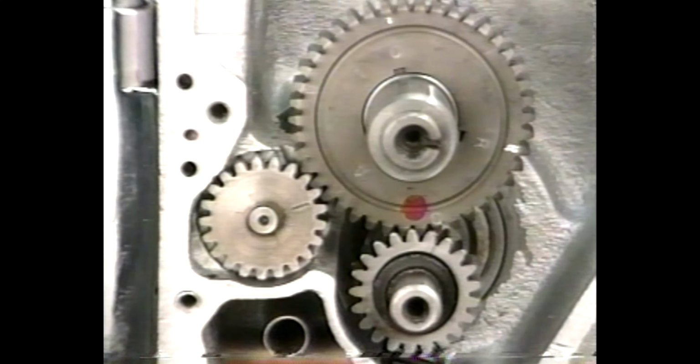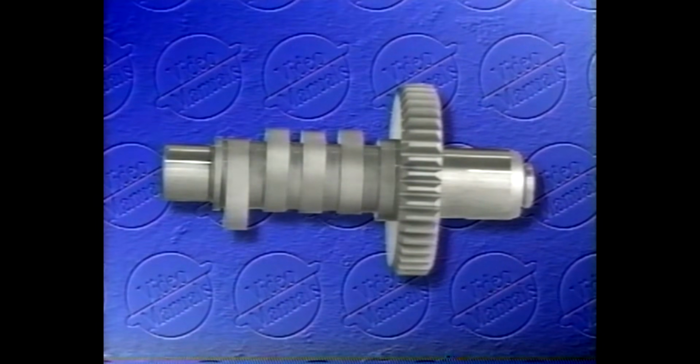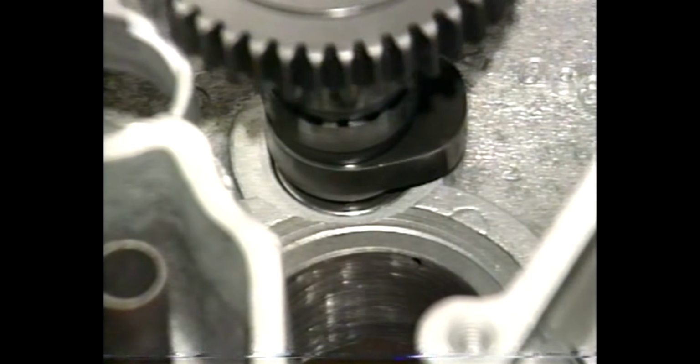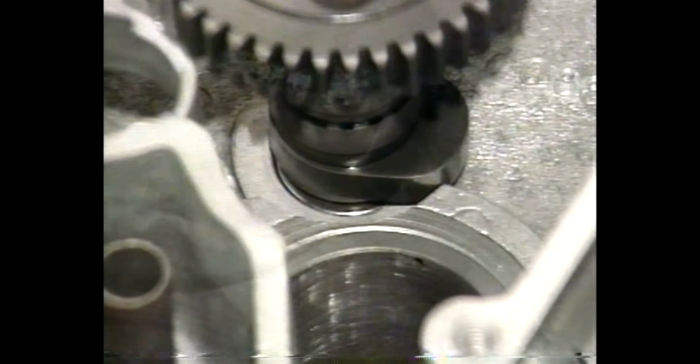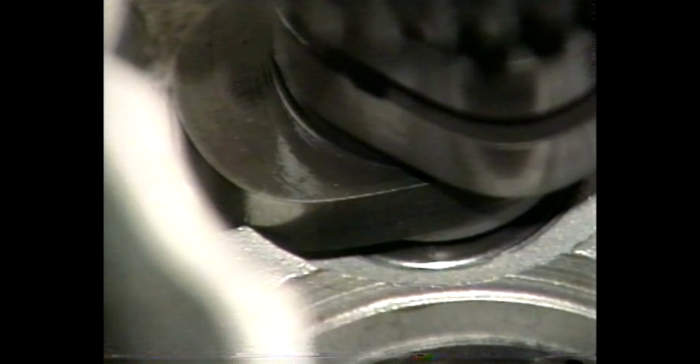When we replace any stock camshaft with an aftermarket high-lift cam, we must make sure that our camshaft, in particular the rear intake cam lobe, is able to rotate freely past the housing for the pinion shaft bearing race in our crankcase. If the rear intake cam lobe is hitting this housing, we must take our crankcase to a machine shop and have them remove the top section of the bearing race housing.